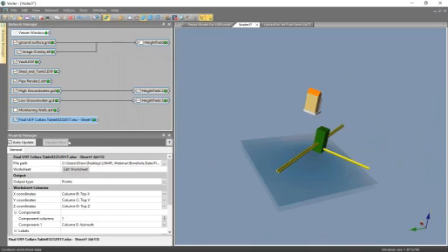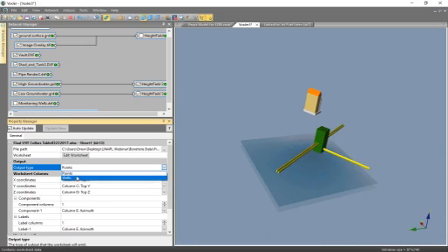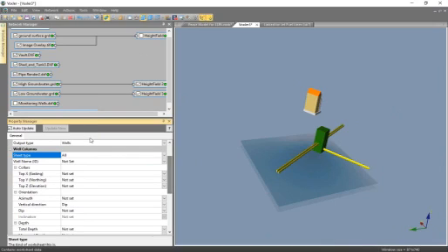And I need to go down to the property manager and set the appropriate columns. So first, if I expand this up just a little bit. Okay, and so first, we have our output type. And since this is borehole or well data, I need to change this to wells. Next, under well columns, you can probably notice that all my columns have changed here. And these will change again as soon as I change this to collars.